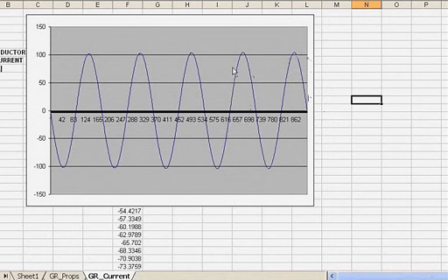But you can see as it gets hot, and the end temperature of this thing was about 120 Celsius, the current is actually slightly rising. It's right on 100 amps there, and it's about 104 amps there, or 102.3 amps there. If you closed up the air gap and ran this again, which I did, then you would see more dramatic changes in current as the device approached its thermal limits. And you certainly wouldn't want to approach Curie temperature with this, because you would get a thermal runaway situation.